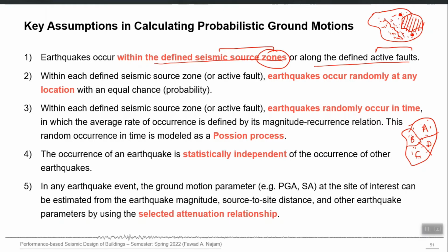When we have some past earthquakes in a particular area but we cannot associate them with any known fault, there may be a fault there, but maybe it is not known yet. In all those cases, we make it an area source. We treat it as a source which produced earthquakes frequently in the past and is also expected to produce them in the future.